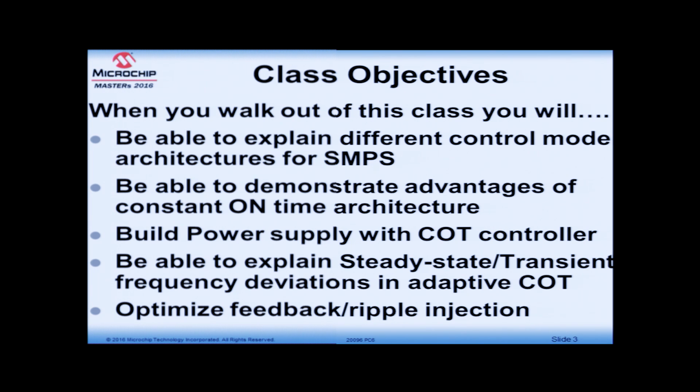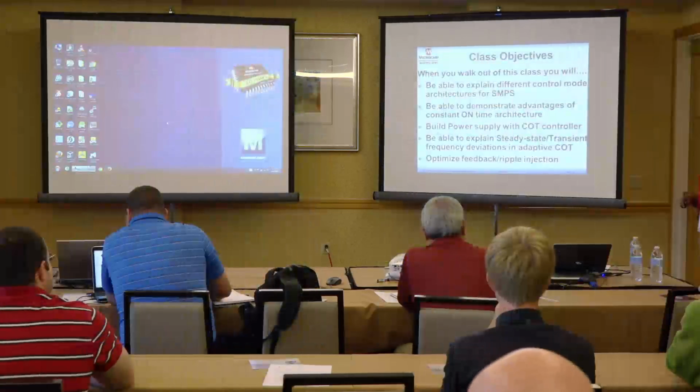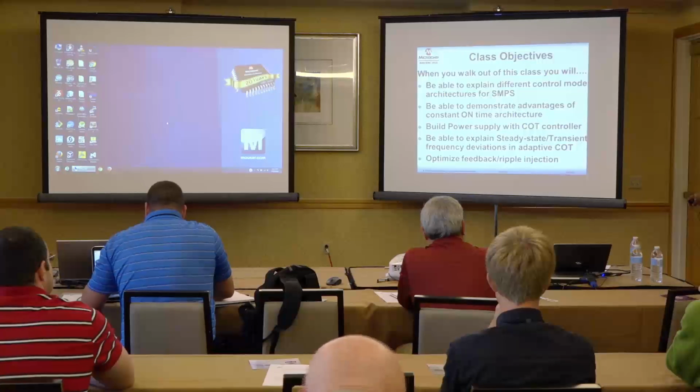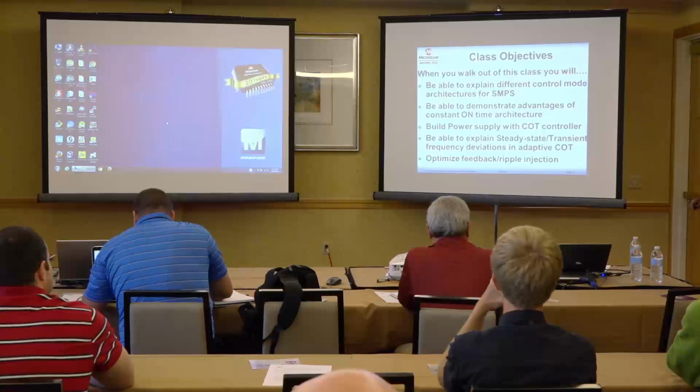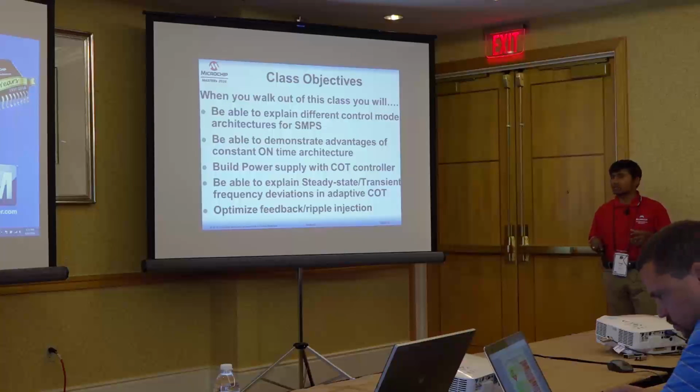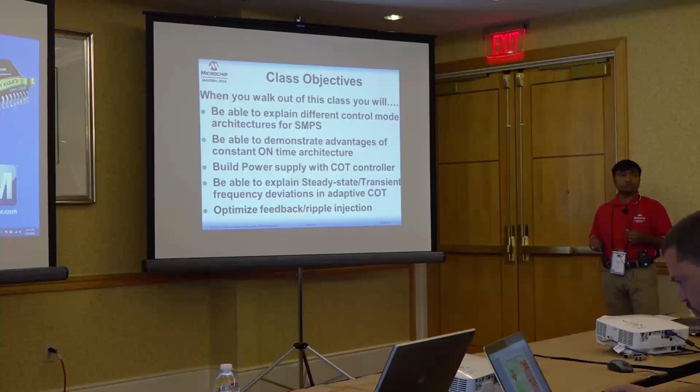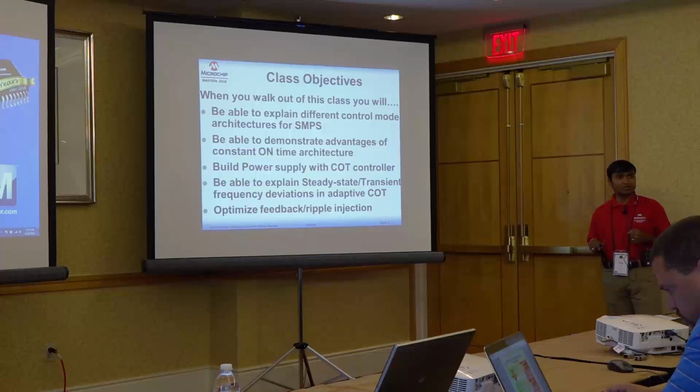You will be able to build a power supply using a constant on time controller. You will be able to explain steady state and transient frequency deviations inherent in adaptive COT, and optimize feedback and ripple injection. Those two sections will be covered by my colleague Paulo.